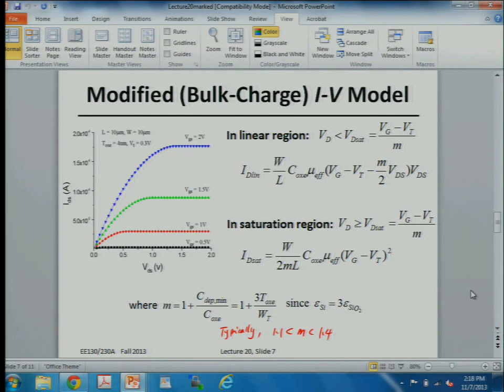Now, that's in the linear regime, right? When the electric field across the inversion layer is just equal to VDS divided by L. But in the pinch-off regime, you're not applying the full VDS across the inversion layer. Okay, so let's say you have the source voltage, and that's the reference voltage. You're applying a gate voltage relative to the source voltage. What is the potential of the inversion layer right at the pinch-off point?